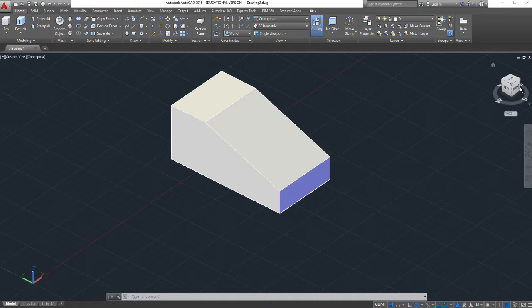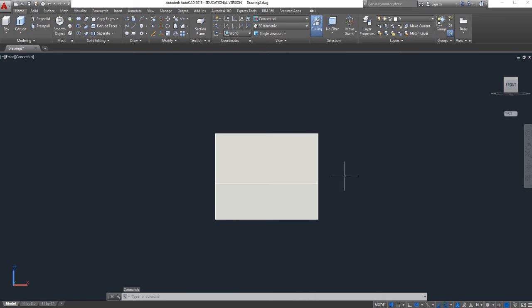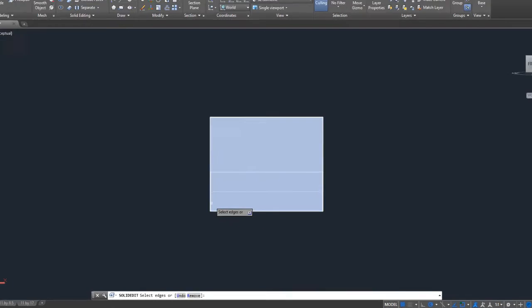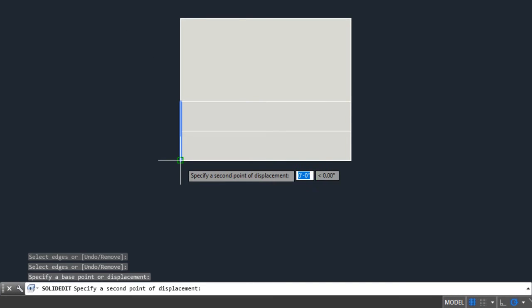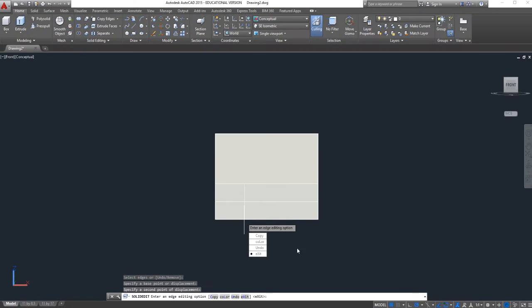If I wanted to go ahead and do this area and make a cutout of it, I could tell it the front. Then I can come over here and I could tell it copy edges, do this bottom one here, make sure it goes to the end. I could put it there. Then I could copy the next edges, which is this small one here, and I can copy and move him over to here. Then I can come over here, copy this edge, this small one again, and I could probably put him here.